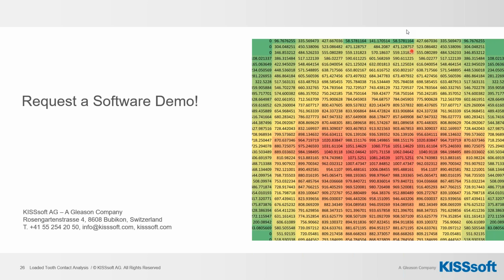So the amount of deformations on the shaft depends on the stiffness of the bearings. How can you account for stiffness for sliding bearings, or also known as journal bearings in KISSsoft? So journal bearings can be modeled in the shaft calculation. It's a separate type of bearings. So in the shaft calculation, you have rolling bearings, you have general supports, and you have journal bearing. And for the journal bearing, you can set a fixed stiffness, damping, and also diametral clearance.